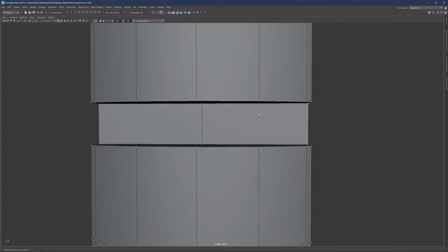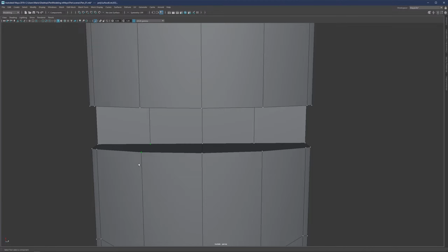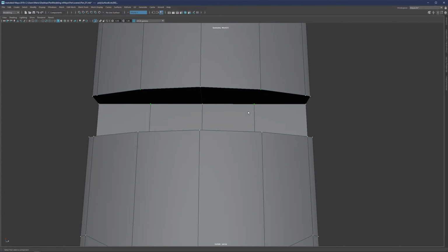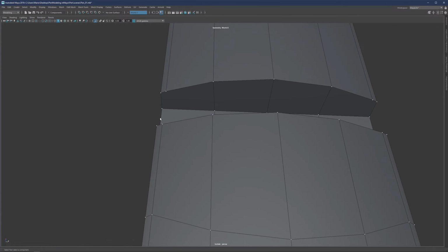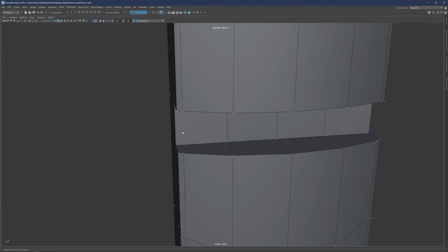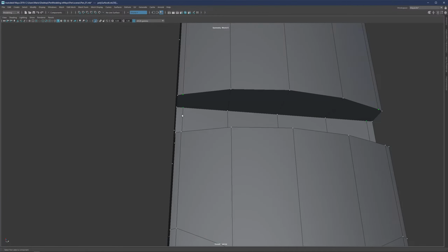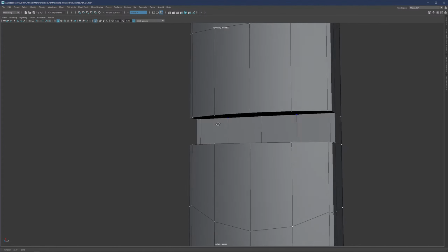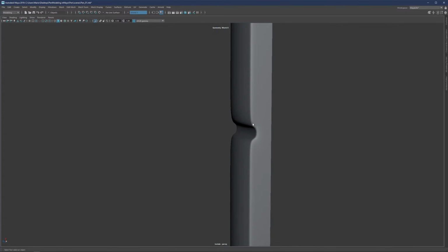And we just need to repeat the same thing here. So I'm gonna just middle mouse click, select these two points, and this time actually we can use symmetry. And let's hit Shift, right click, and connect components. And these two will hit G, it will just repeat the previous operation. All right, and we have one final loop left. So we need to just close the open edges, connect components, Shift, right click, connect components. All right, so when we subdivide, we have something like this.